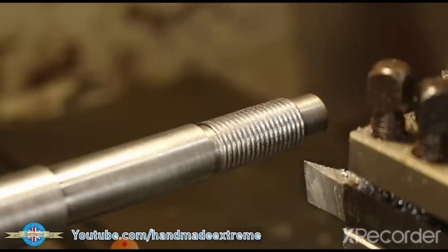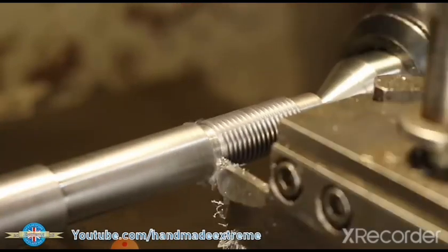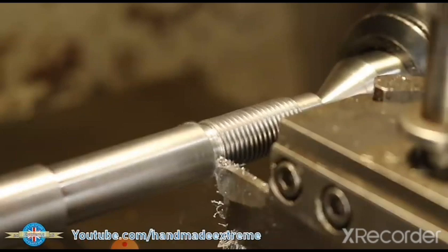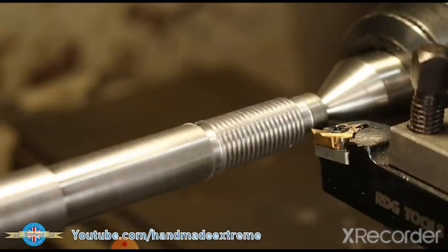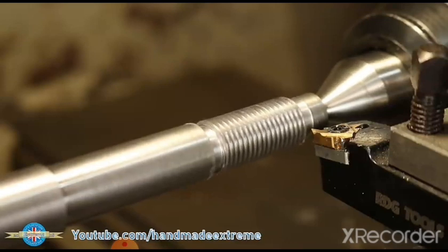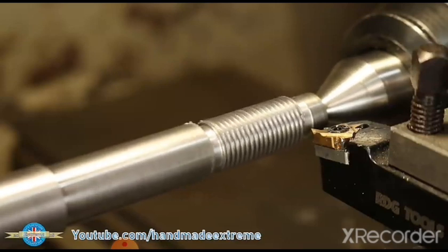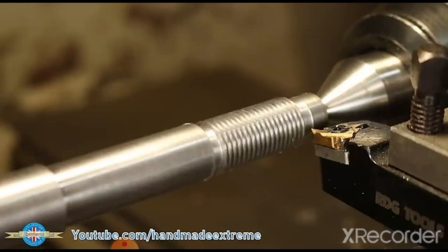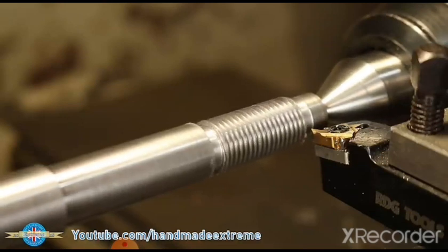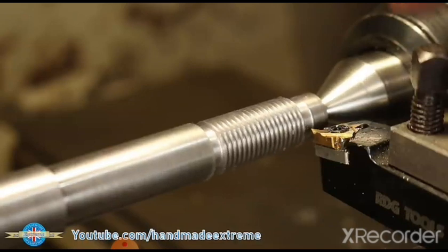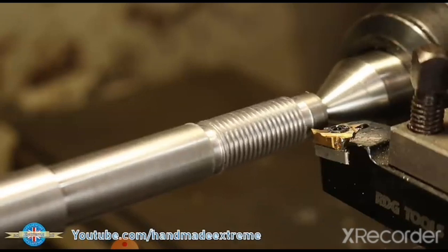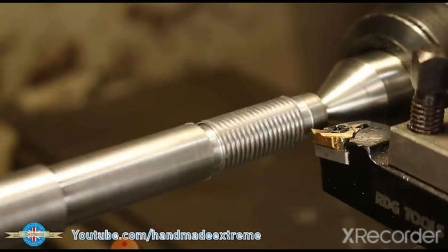So let's give that a go. As a little tip, because I've swapped the tool out and done a load of other operations, what I like to do is just put the tool back in, get the machine going, and then do a cut without actually having any cut on, just to check that the tool lines up with the root of the thread. So you really don't want to screw it up at this point.